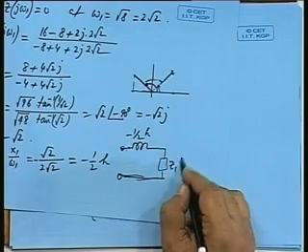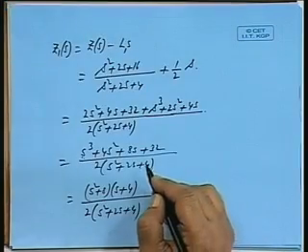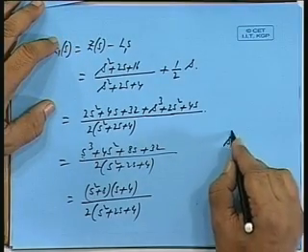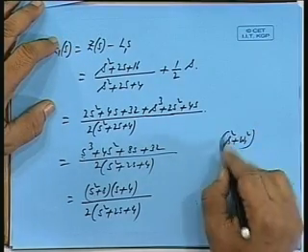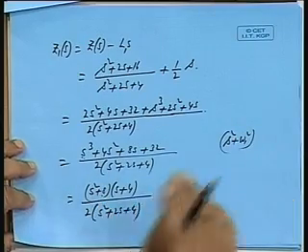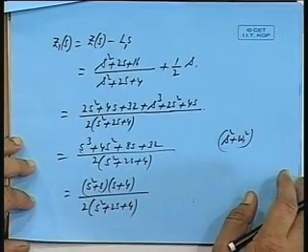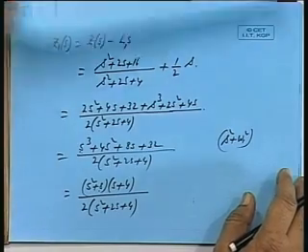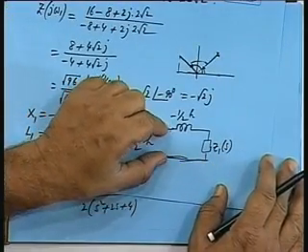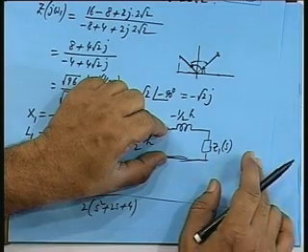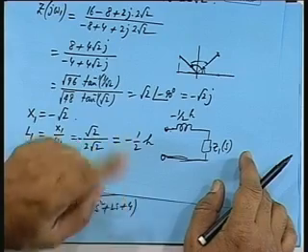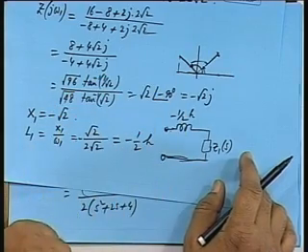So, this Z1(s) at omega 1, that is 2 root 2, that is s squared plus omega 1 squared will be a factor in the numerator, and omega 1 squared is 8. So, s squared plus 8 will be a factor, that we know. Because what we try to ensure is this impedance at that frequency is equal to the reactance at that frequency of this coil.